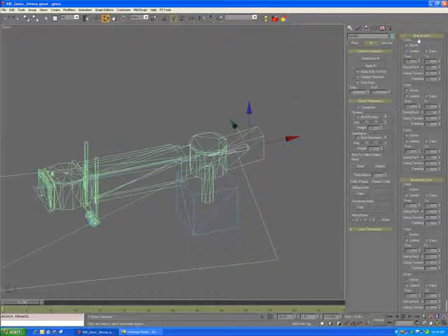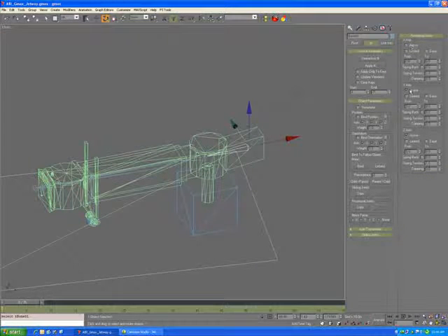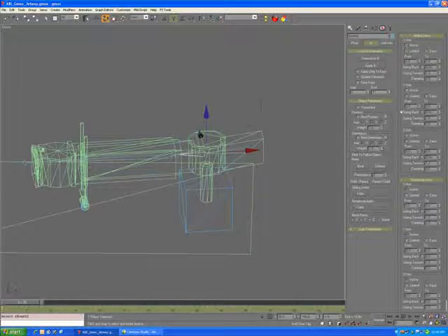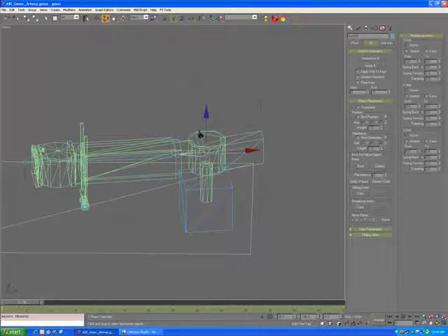And so you see there's sliding joints and rotational joints here. Well, we're just going to turn off the rotational joints, because this really should not move at all. This is the root node. It doesn't move anywhere. So then we'll go to the next joint. This has no sliding joints, and by default sliding joints are off. So since this has no sliding joints in it, we'll just focus on the rotation.